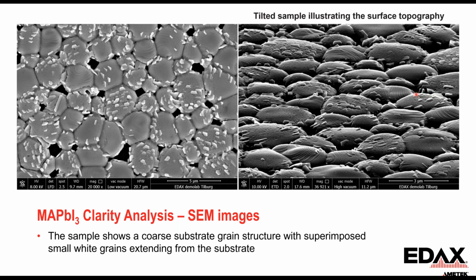So this is the image on the left, and remember we tilt our sample to 70 degrees for the EBSD analysis. As we do that, these grains have some topography. If we think about where the EBSD detector is positioned, as we position the beam along this topographical surface, there are only certain faces that are oriented towards the EBSD detector and that we can also hit with the electron beam to generate a pattern.